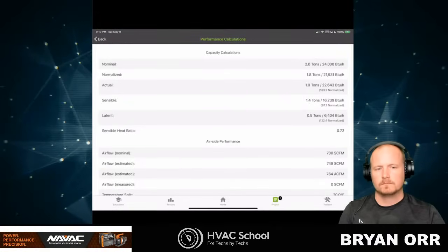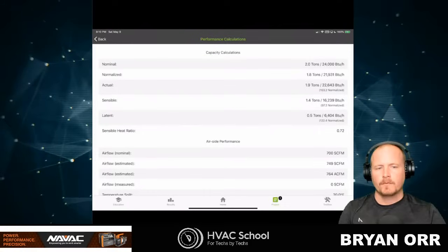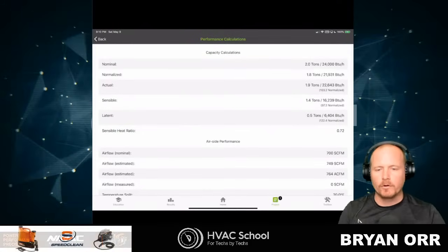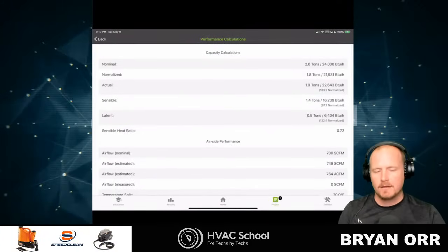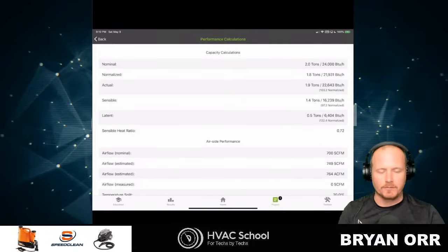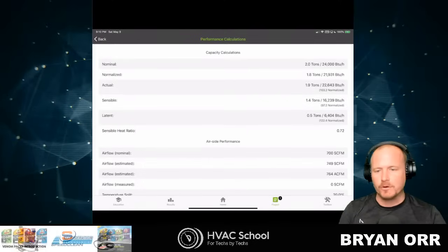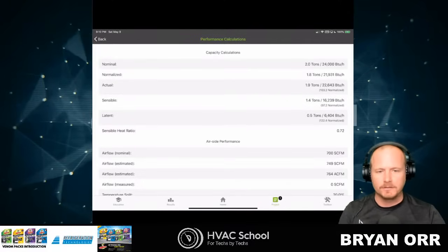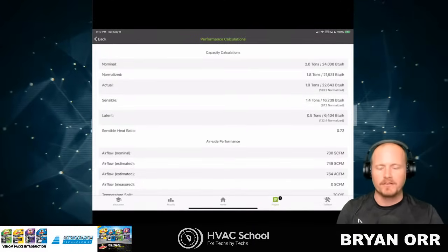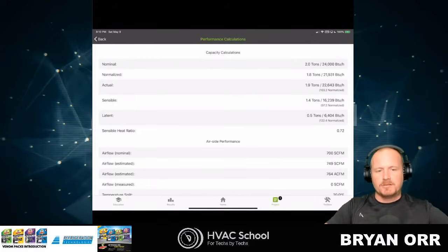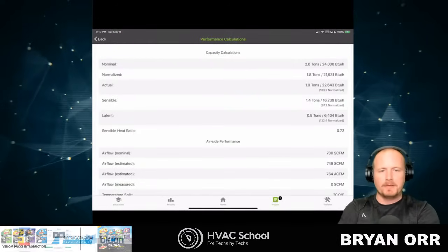Otherwise, you get mold growth. And that's why in a dry climate, to optimize for sensible capacity, you do things like really drive down your compression ratio as much as you can. You use oversized evaporator coils, you run high airflow, and you do everything you can to optimize your compression ratio to be a little on the exotic side.